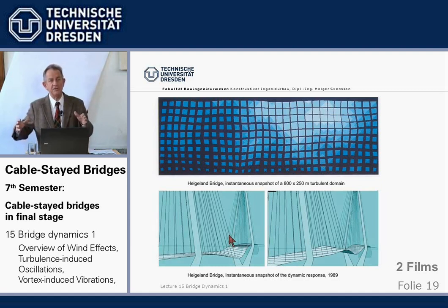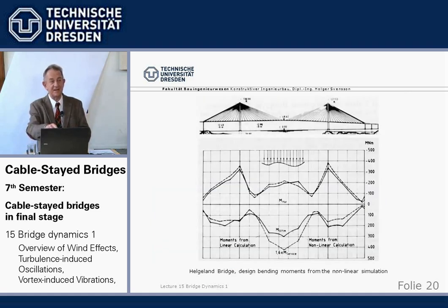And we use the results from the wind tunnel with the part section model to let the computer find out what forces, lift, drag, moment, are exerted from this wind onto this structure. And then, I come to the film in a moment, as a result we can directly, from the computer, get the moments out of that. So we don't have to recalculate backwards, forwards, but do it all by computer.